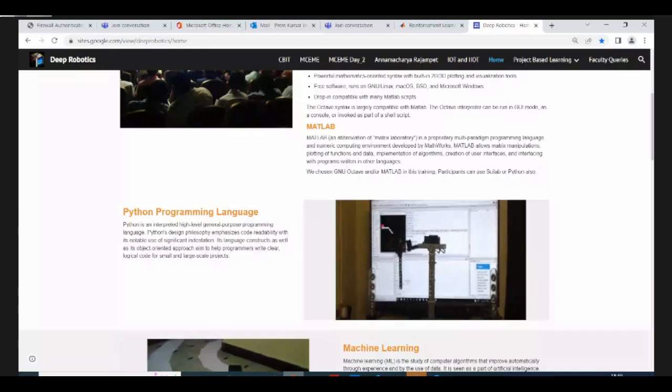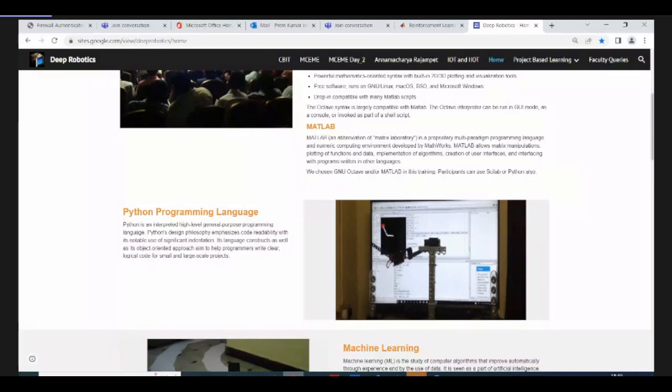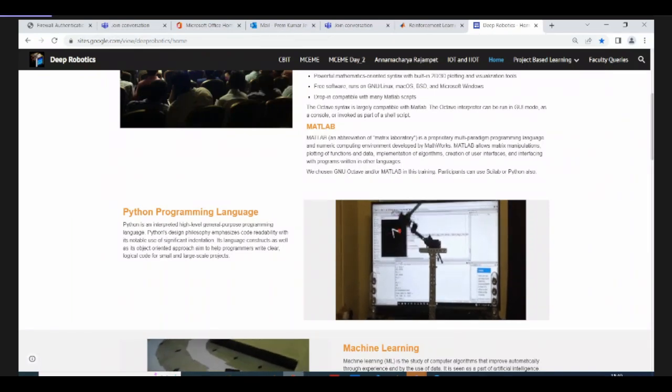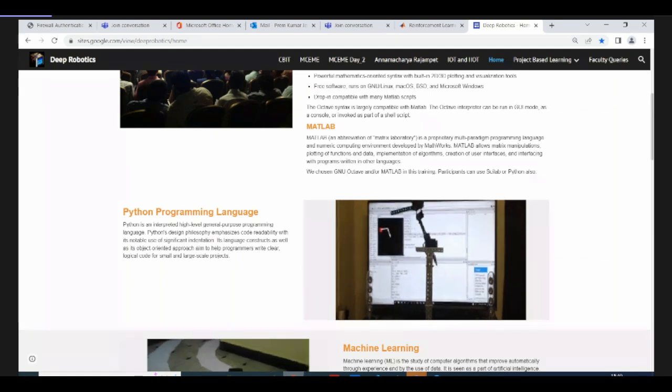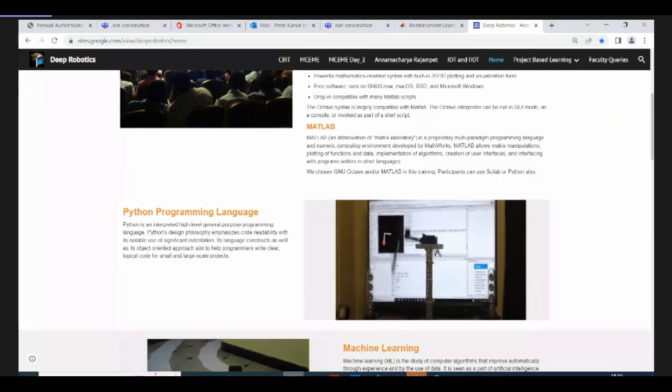Just you can see. That means shoulder angle and elbow angle we're able to measure. And since the servo motor can't give 360 degrees, I'm using 2 servo motors. Okay, so over there even I can use the stepper motor, but still I'm going with servo motors because students are very familiar with servo motors. So in this way we can train up.